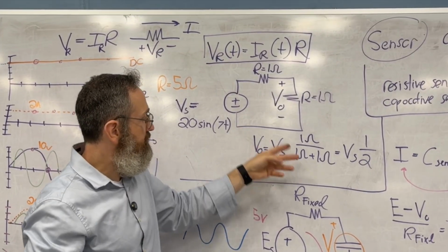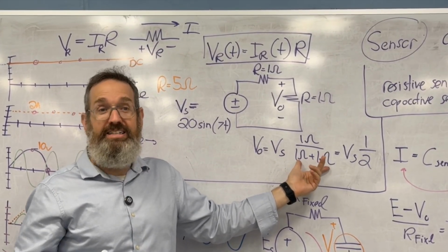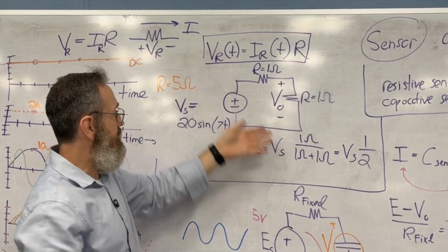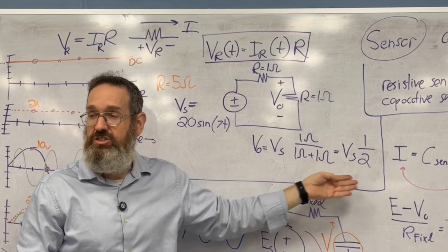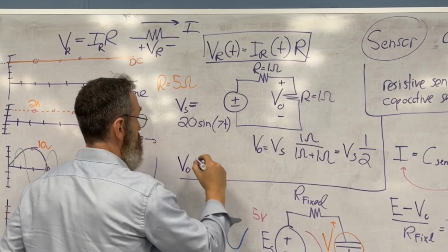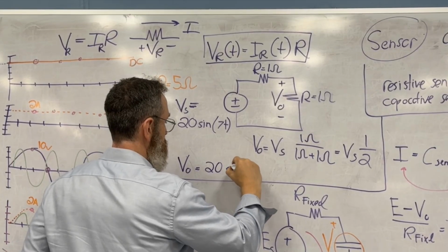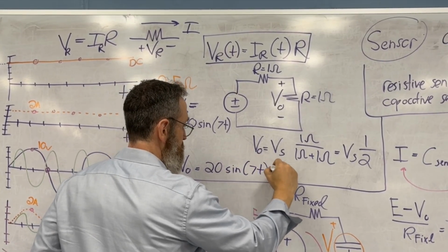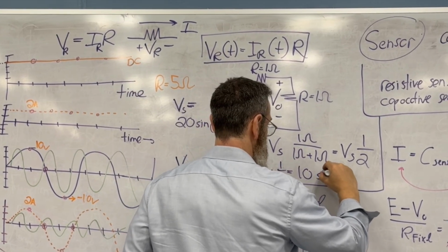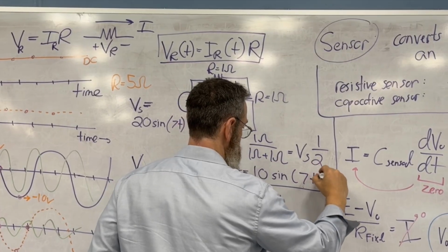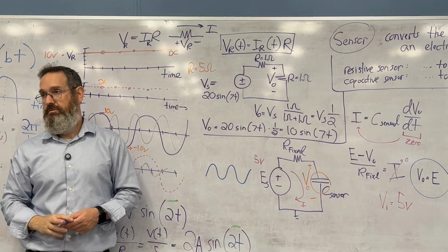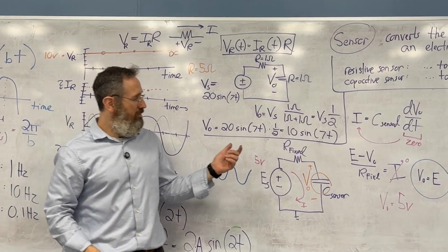The way you derive this equation, if you're right, is by applying Ohm's law, right? I don't want to go through it again. So the voltage divider equation, just like Ohm's law, is still in effect, and so therefore we can write V out is equal to 20 times the sine of 7t times 1/2, or 10 sine of 7t. That's sinusoidal steady state analysis. And let's do the check.